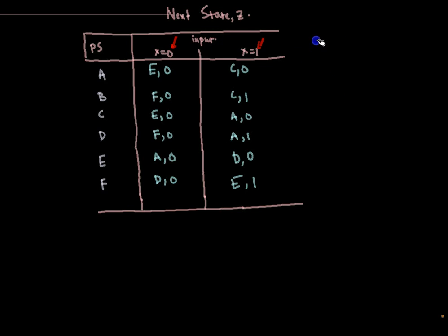Now as we have earlier discussed the definition of state equivalence, if we find that Si and Sj are equivalent for any input string of any length, then we can eliminate one of them from the machine to minimize the machine. So we can use this technique to minimize the machine. I'll be doing that for this example.